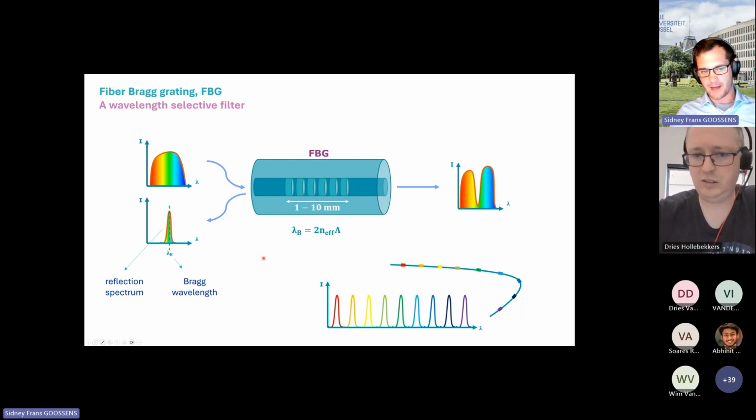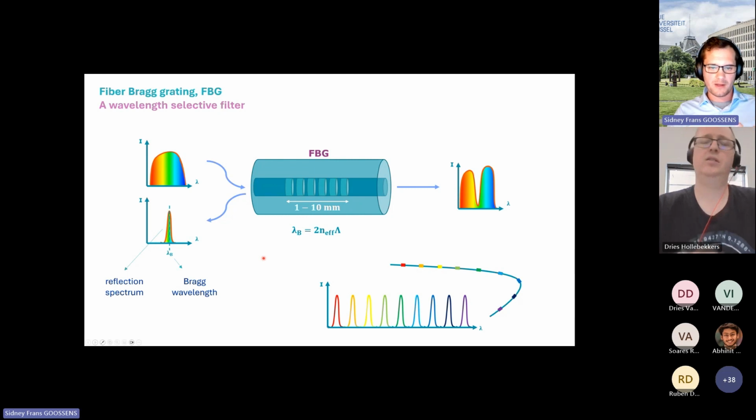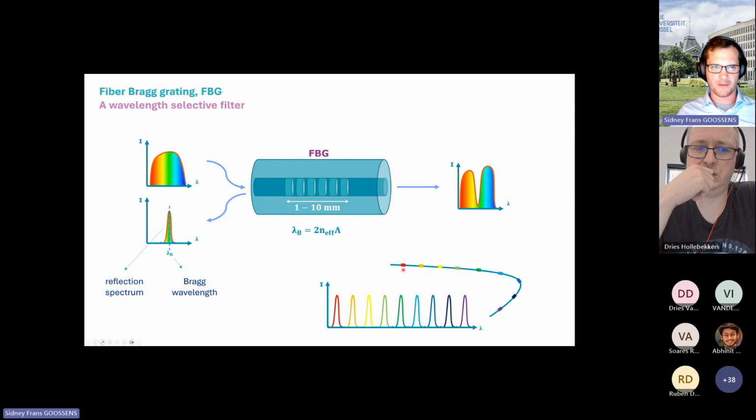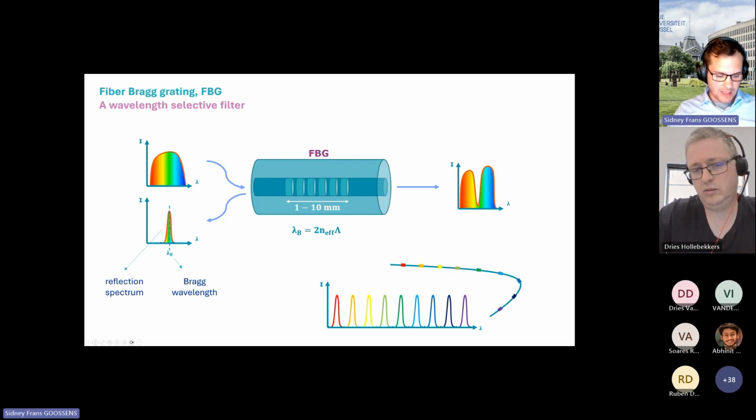Typically what one does is install the sensors for strain measuring on the structure while leaving one optical fiber sensor, included in the same fiber, that is not directly installed on the structure. So it sees the temperature of the structure, but it does not see the strain induced by the structure. That can be done by including that one sensor in a capillary, for example, so that it is not influenced by the strain, but it is influenced by the temperature. But to answer your question briefly, indeed, they are cross-sensitive to both strain and temperature.